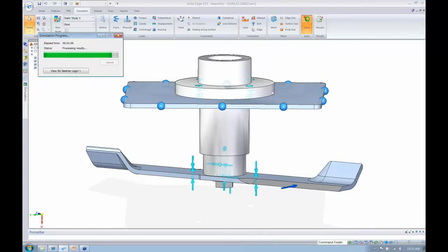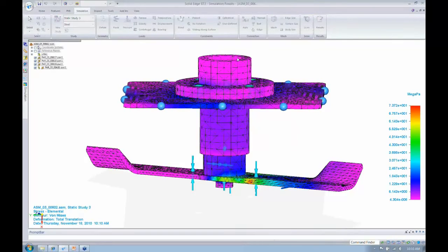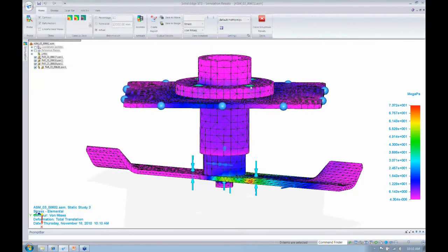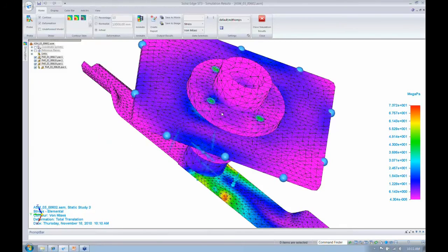The other thing, real quickly, that is new with Solid Edge Synchronous Technology Simulation 3, ST3, is that if, let's say, your area of concern is a hole or a bolt hole like this, we now have offset surface, so I can put an offset surface around this ring, around this bolt hole if I wanted to, and put a finer mesh inside and a coarser mesh outside. Now I can't have a tiny mesh inside and a huge mesh outside. You have to step it out. But that'll at least allow you to not have that tiny mesh everywhere and drive up your solve time.